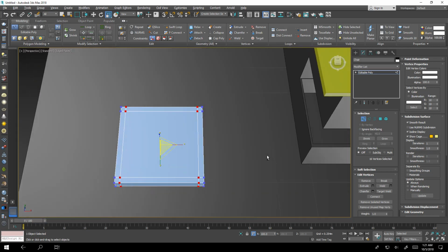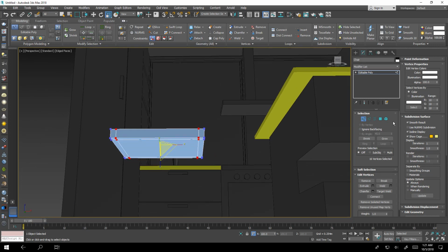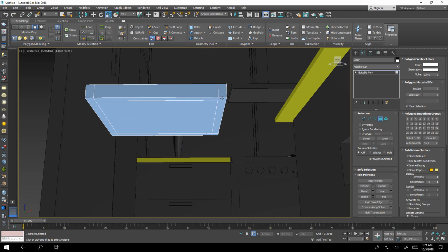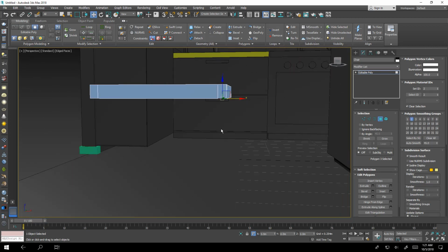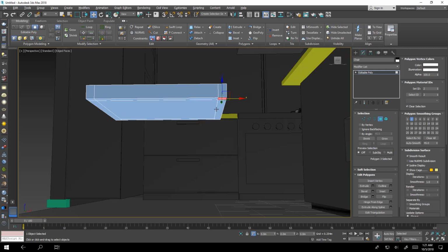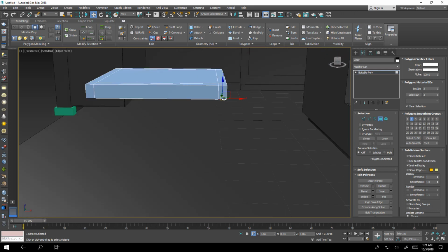And we will go after this to make our selection from the polygons. I will test here for one leg. After selecting the polygon sub-object, I want to extrude this polygon towards our ground by 0.5 meter or 50 centimeters.